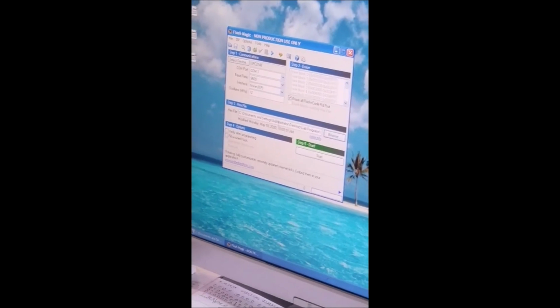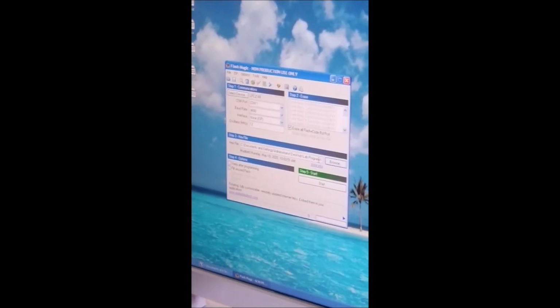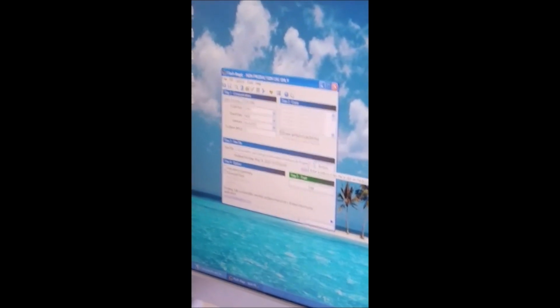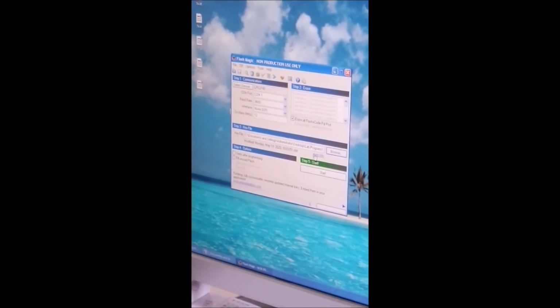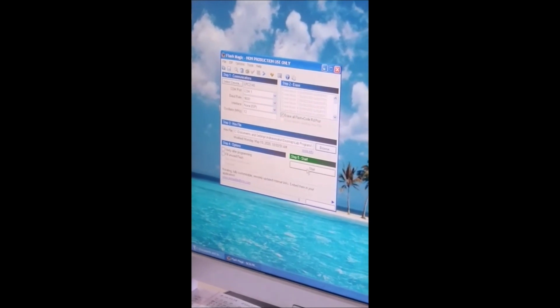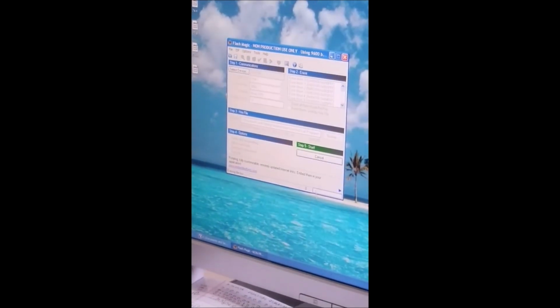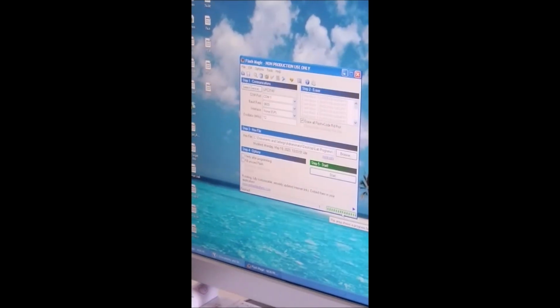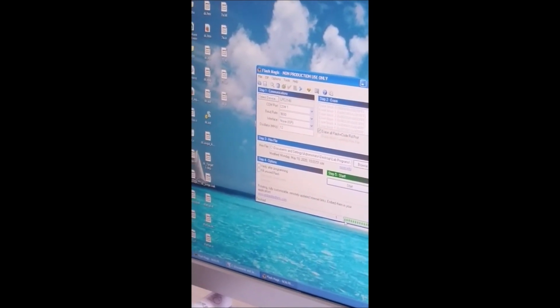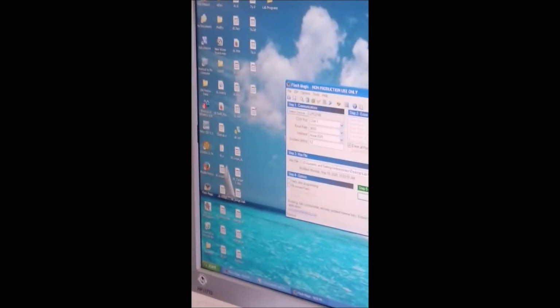So now the file has been linked to the hex file in the location. The location should be given here. Then after that you need to click on the Start button. When you click on Start, it will take some amount of time to get dumped to the microcontroller. After finishing, you can now see the output.